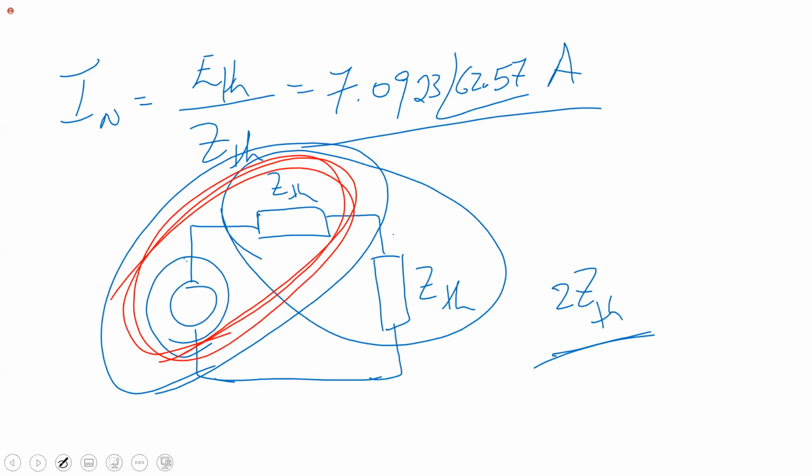That's the equivalent circuit at those terminals. So when you add this, the total impedance in the circuit will now be 2Z Thevenin. Okay? Because maximum power. Which means that the supply will be supplying that total impedance.